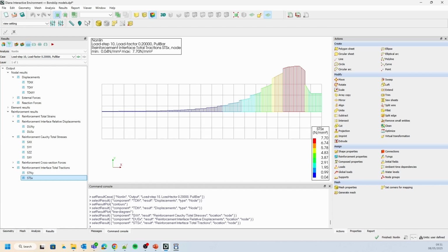As shown in the result, all sections of the backbone curve that I presented earlier can be clearly seen in the shear traction distribution around the bar. The linear part, the exponential, and the drop of the stress, and after that, the constant value for the S3.